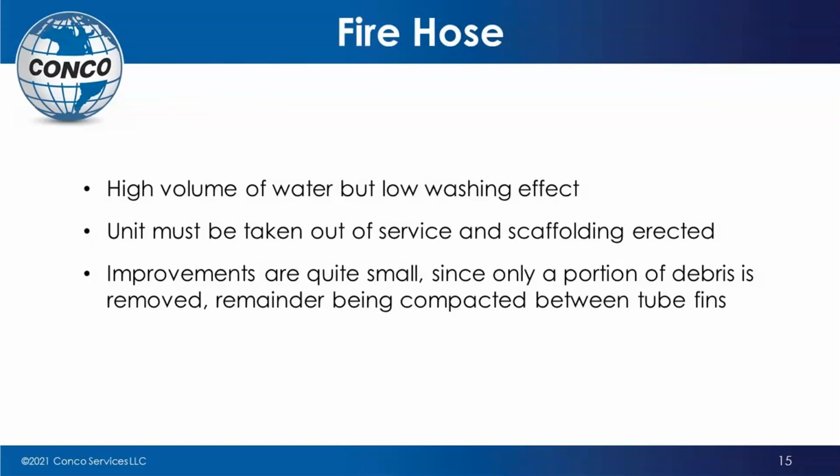The fire hose itself has a very high volume, but it's got a very low washing effect because it's got a very minimal pressure. So what happens is the fins closest to that hose do get the weight of the water and the pressure coming out of that hose directly, and you are able to remove all the loose debris, and maybe you can actually push some of the debris in the fins out.